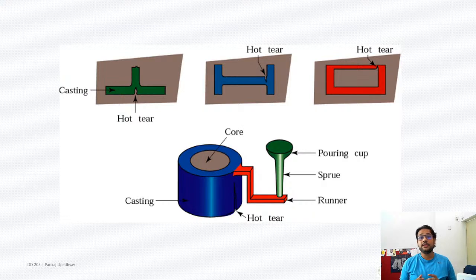Okay, and when the material shrinks, most designs are not flat and straightforward, they are slightly complicated. There are slightly larger volumes in some places, smaller volumes in some places, and some features which are extruding out of the surfaces of the part. So because of these changes in dimensions, changes in form, there are some places which have more stresses because of thermal expansion and contraction of the material.